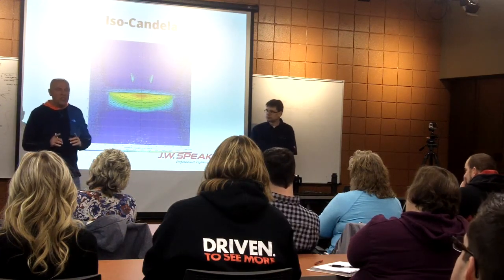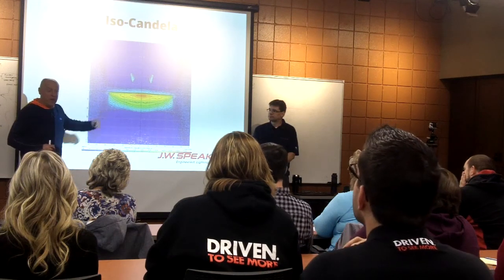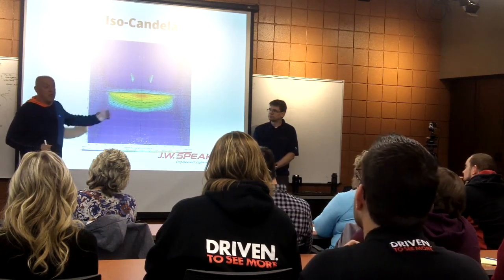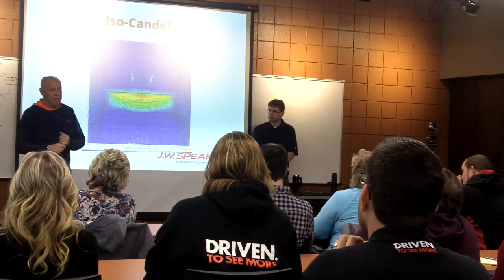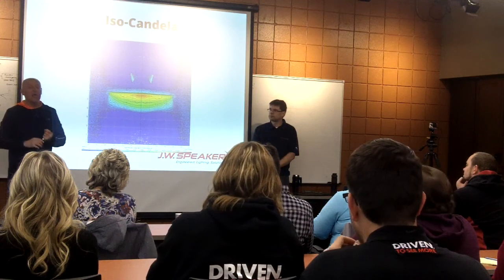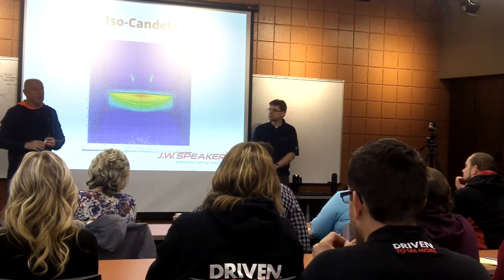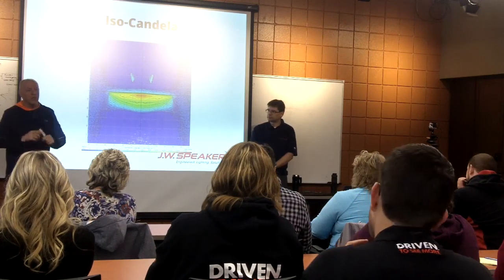And both pieces of information are correct. So I can say my lamp performed 500 lumens or my lamp performed 1,000 lumens. It depends how big the window is. It's good information for you to know when you look at some competitor isocandela diagrams: how big the window is, what they're looking for.